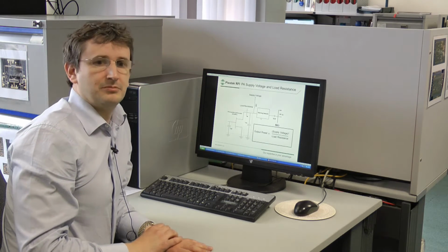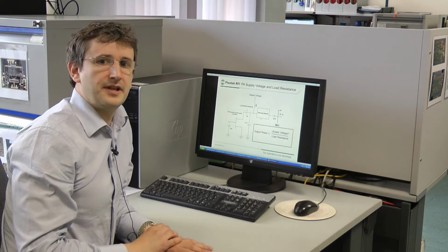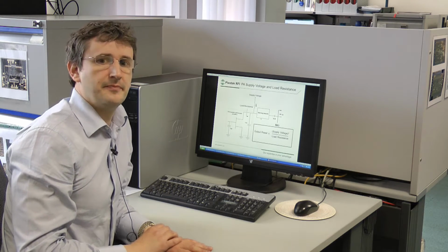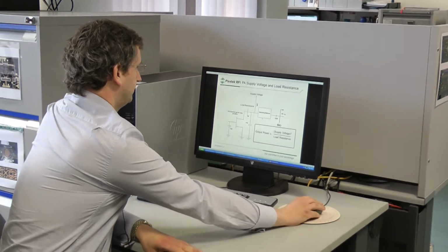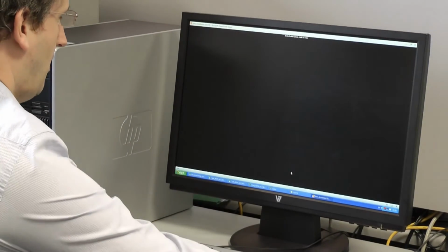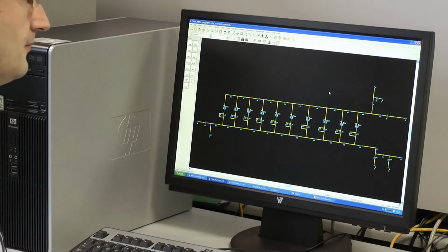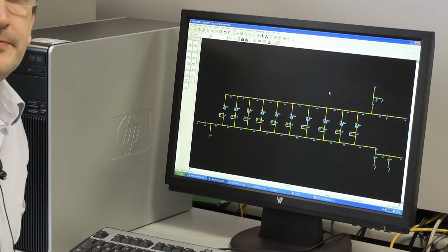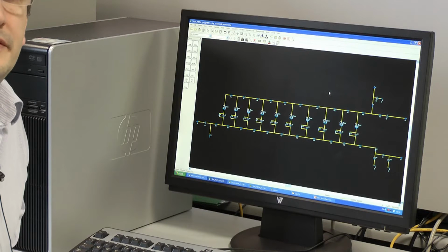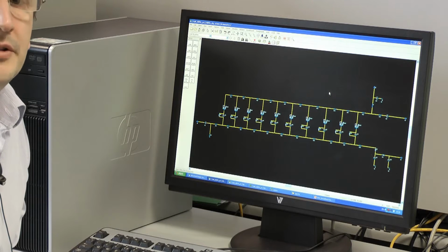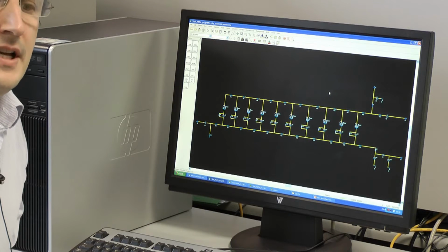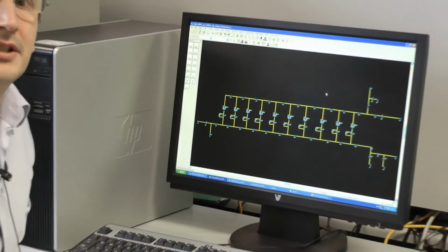A gallium nitride power amplifier will have around 5 times the output power of a GaAs pHEMT power amplifier MMIC operating over the same band. The design we're going to look at today is a power amplifier operating over the 2 to 18 GHz band. It has flat gain and high output power. It uses the non-uniform distributed power amplifier architecture, or NDPA. It is designed on a gallium nitride on silicon carbide process.